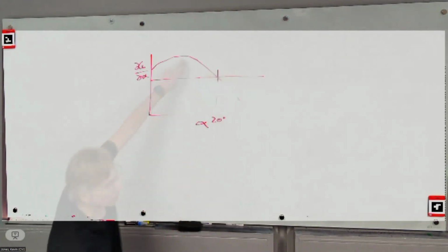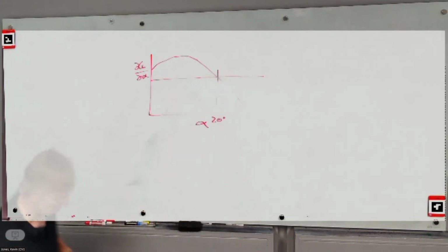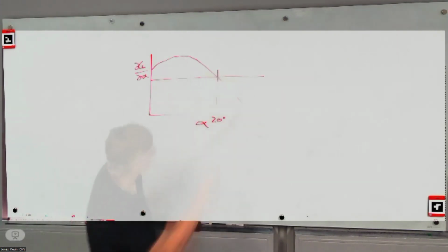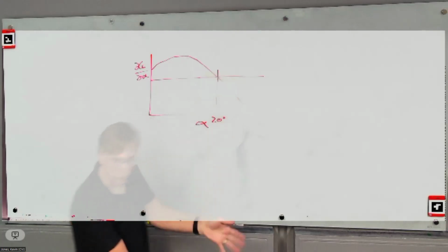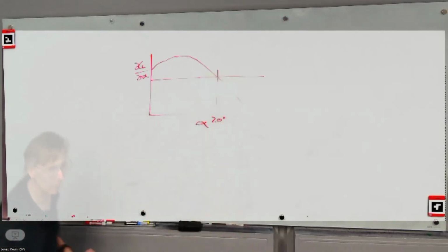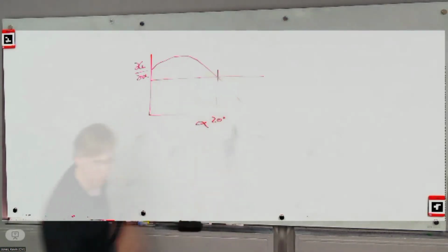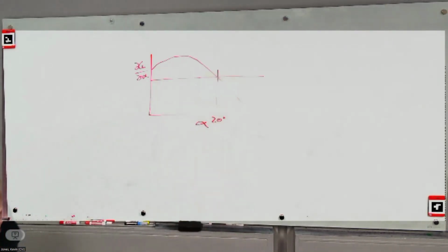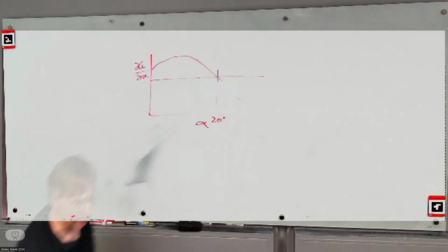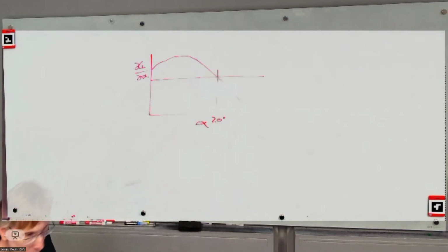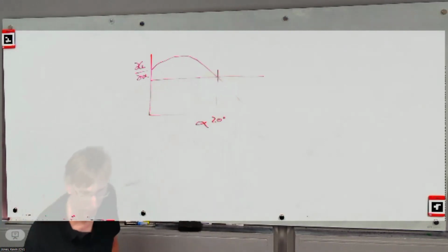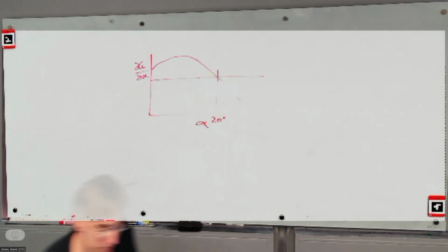So there's this pocket where CFX actually over predicts VLM. And then eventually, I think we're probably starting to see stall on the forward part of the wing, so it's starting to separate. Neither of those 2 pieces of physics are captured by vortex lattice methods, though it has its uses. Anyway, you'll do a plot like that, only for the subsonic. For supersonic, VLM doesn't work.